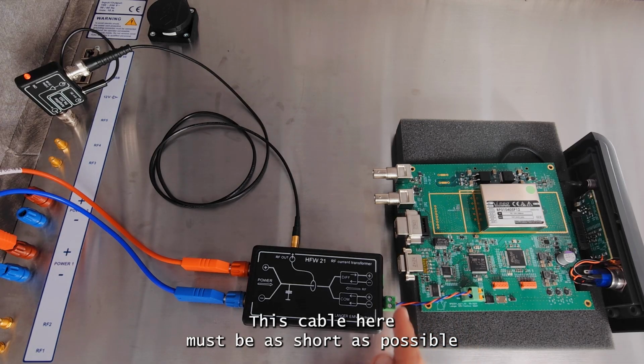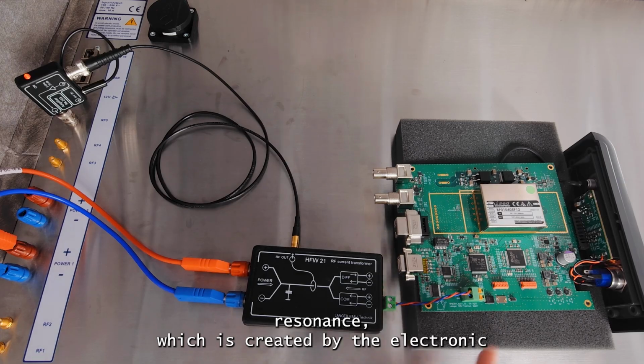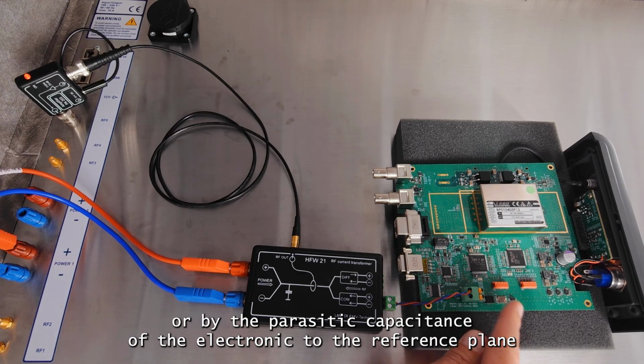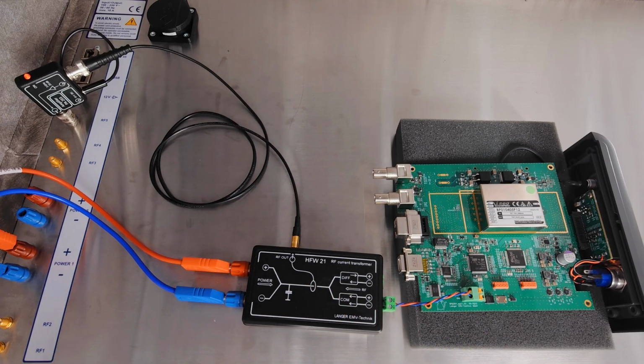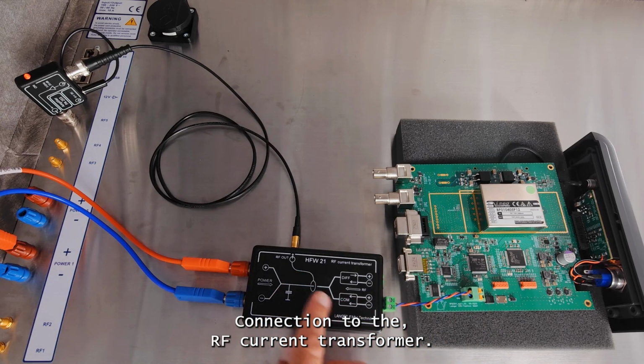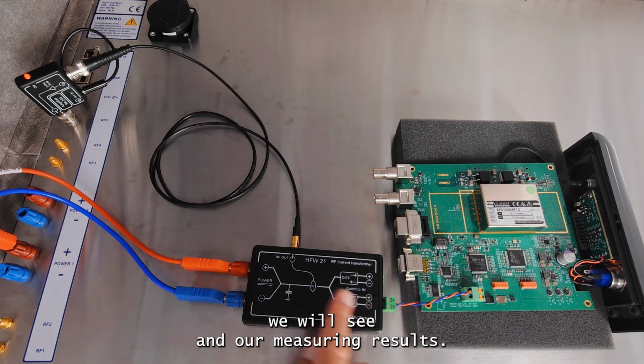This cable here must be as short as possible because of the resonance which is created by the parasitic capacitance of the electronic to the reference plane, and the inductance of our connection to the RF current transformer. And later we will see exactly this resonance in our measuring results.